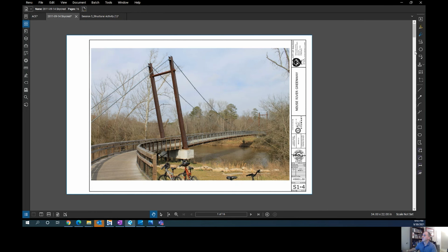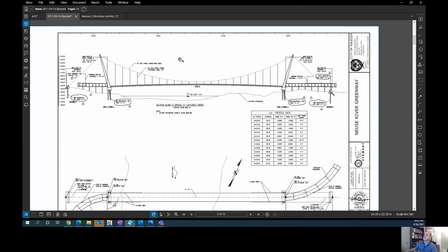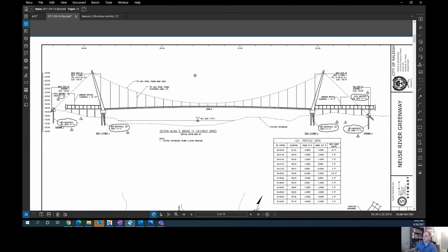And what you'll see is it is a suspension bridge, as Charlie talked about already, and it is resisted by our primary pier elements, the ends, which are in compression, and our primary tensional elements, which are those smiling cables. Things that smile are in tension, things that frown are in compression. Simple way to think about it. So here's the side view of that bridge. And what you'll see here, again, are those primary tension cables running in that smile shape across the bridge span.